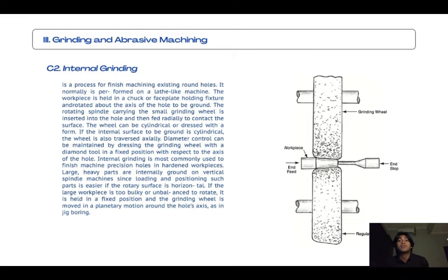Okay, next is horizontal spindle surface grinding. A surface grinding with a horizontal grinding wheel spindle. The wheel cuts on the periphery. The table may be either circular with rotational motion or more commonly rectangular with a reciprocating motion. In both arrangements, the wheel advances perpendicularly to the basic direction of motion with each cycle of table movement, and thus generates a flat surface.